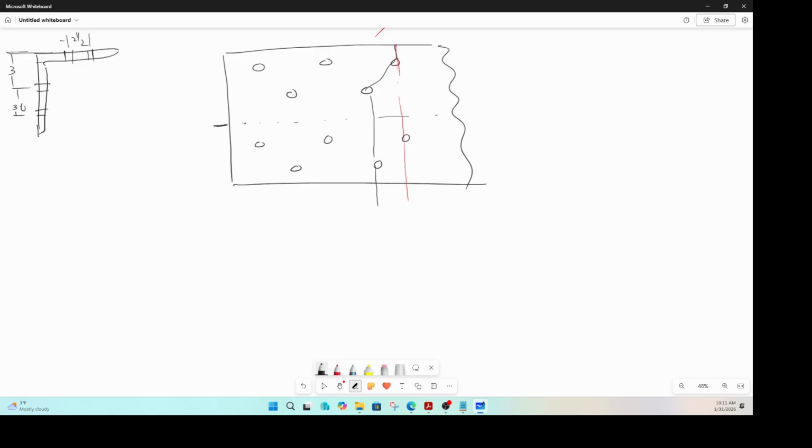For example, the distance between these two bolt holes is called the gauge distance. And that gauge distance is not a straightforward value. I think this is from here to here, it is another 2, right? Or 2.25. Let me see here. Anyway, to calculate this gauge distance, you need to calculate that distance and this distance, but then subtract one thickness. This is the kind of problem that we will do in the next session.